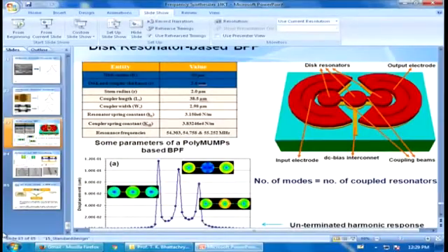In a nutshell, three important characteristics you have to look at in a frequency synthesizer are the frequency stability, the phase noise, and the settling time. Secondly, power consumption. You can have very good performance, but if your power consumption is heavy, 10 milliwatt, actually you want to design finally a sub-milliwatt transceiver. So the frequency synthesizer being the most power hungry design, think of the challenge: how to make a frequency synthesizer which consumes even less than 1 milliwatt of power.